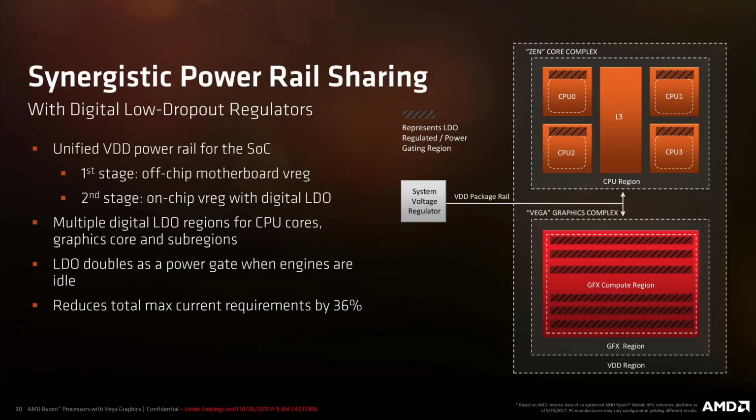A quick word on bypass mode. As with previous platforms, AMD extensively uses fully digital integrated voltage regulators. The voltage regulators are ultra-high efficiency digital low dropout, or DLDO. Most of the power domains, including the CPU cores, caches, fabric, and so on, have DLDOs that can be controlled individually. However, most of these DLDOs are permanently bypassed on consumer parts like Raphael. That means that regulators are disabled and the voltage regulation takes place on the motherboard via the VRM.